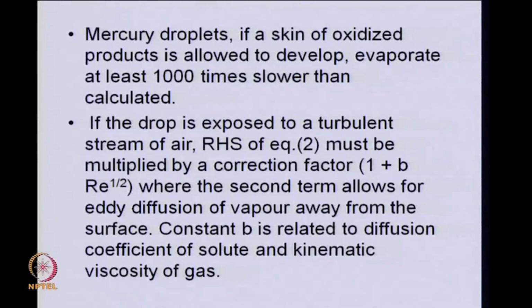The velocity, density, viscosity and drop size all would come into picture. That will be all combined in a dimensionless number, the Reynolds number, and we expect the physical properties also to come into picture, the physical properties like viscosity and diffusivity, right. So, resistance under turbulent conditions will be lesser, or the evaporation rate will have to become higher if we have turbulent conditions.